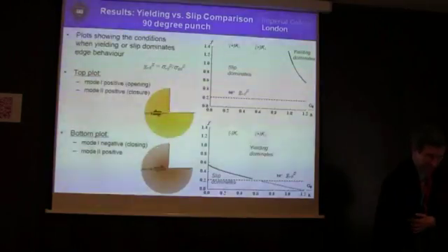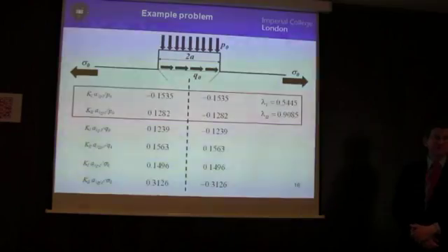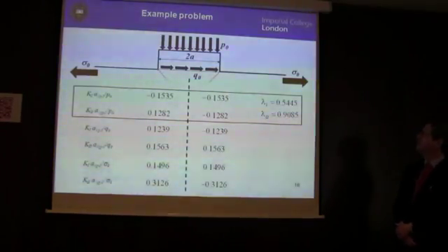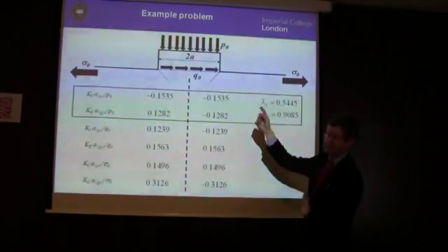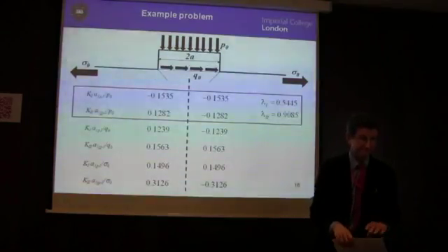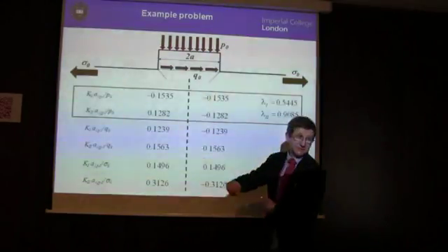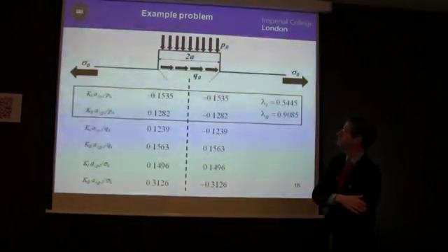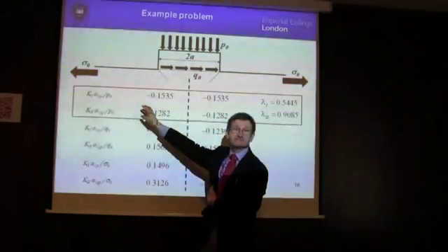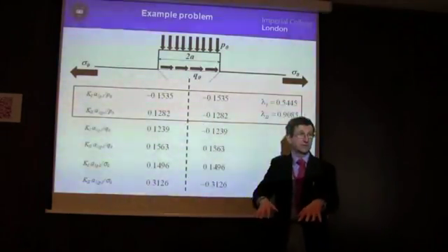So I'll just conclude by applying it to one problem, so you can see how the normalisation works out. So you've got this block problem again. And let's just consider one kind of loading. So let's just push down on it. So we're not going to drag it. We just push down. So P0 is the applied load. A is the size of, or 2A is the size of the pad. And these are the calibrations for the stress intensity factors. So you know how to calculate the K1 and the K2 given the P0.